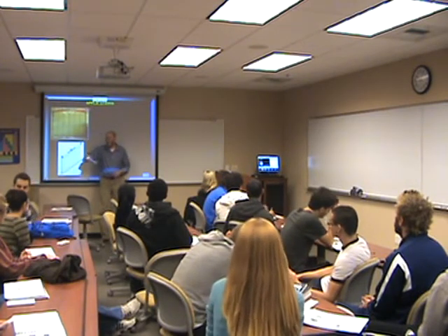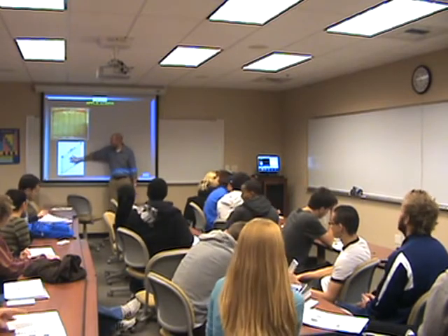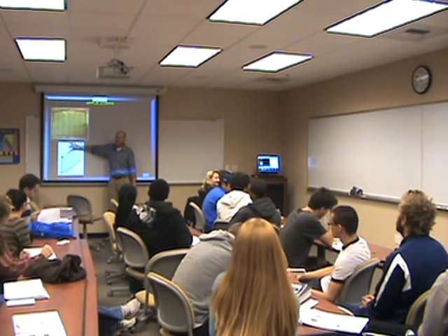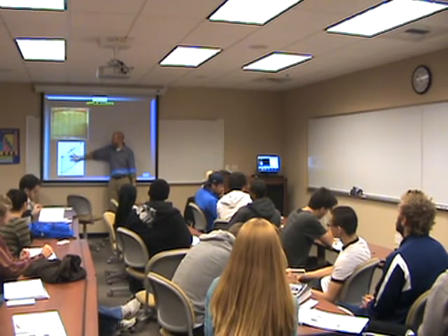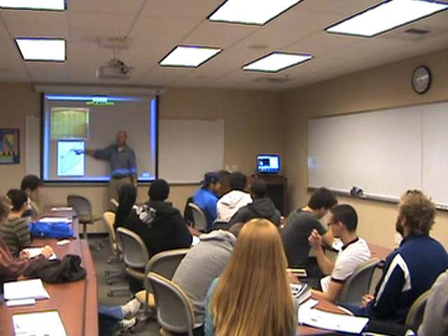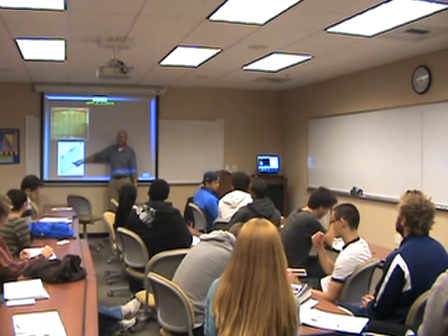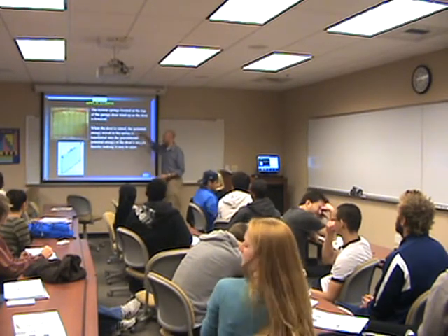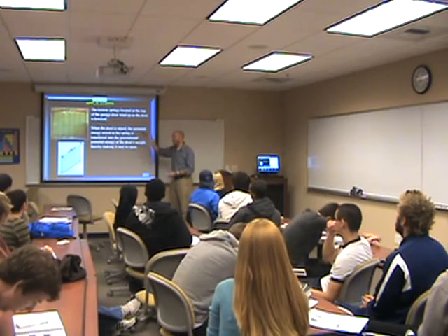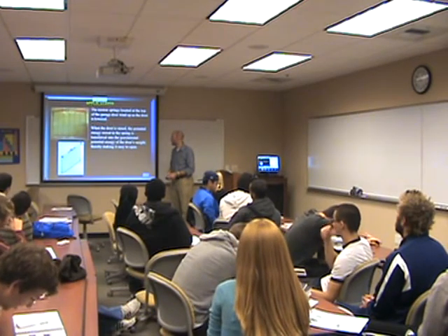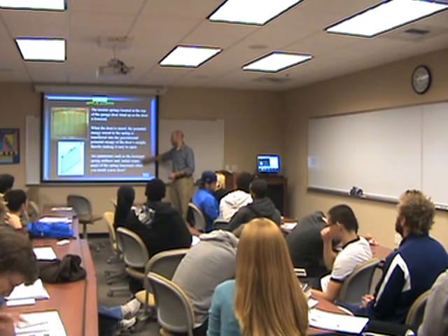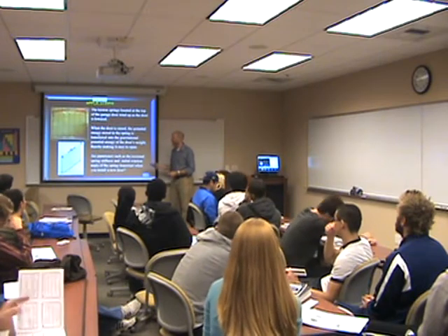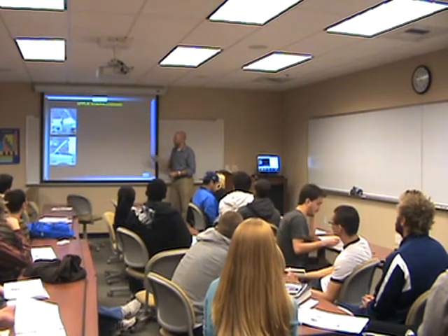Basically, as this goes up, you'll get more potential energy. And so what you want is the potential energy lost in the spring to equal the potential energy gained in the door. If that's the case, then the only force you need to apply is the force to accelerate the door. You don't have any lifting force. And so you can relate the torsional spring stiffness to the weight of the door so that everything matches up nicely.